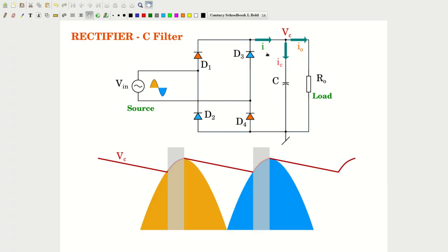And during that time only we will see a current I flowing. So what should be the type of the current? The moment the diodes turn on at this point, a voltage source is seen connected to a capacitance. So there is a direct connection of two potential devices. So there will be a huge current rise here, and it is limited only by the track inductance, diode impedance, and any ESR of the capacitance and the inductances here. These kinds of non-idealities only will limit the current. So the current wave shape will be something like this.